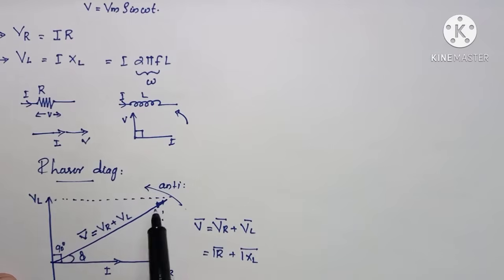And here we are discussing the flow of alternating current through this RL series circuit, and in this series circuit, the current lags the voltage by an angle phi, and this phi is located in the first quadrant, so we can say that it is less than 90 degrees, and it is a positive value.